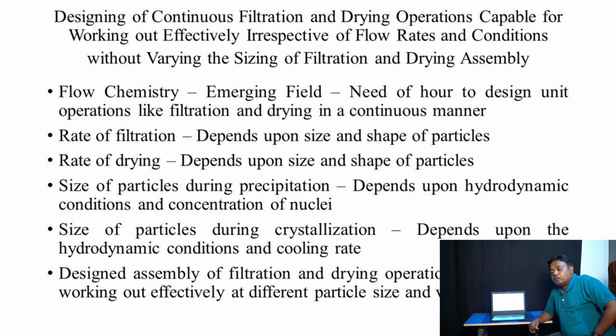The other aspect is that as the particle size increases, the surface area per unit mass decreases. Therefore, the total moisture adsorbed on the surface of the solid particles decreases, and therefore the drying rate reduces.